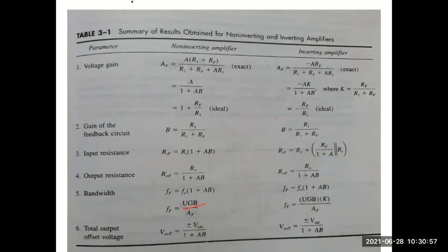It is the voltage which is present at the output irrespective of both the input terminals being grounded. I showed you the case other day. Though both the input terminals are connected to ground, there is always the possibility that there will be some output voltage which is not 0. Ideally speaking, without any input, the output should have been 0.